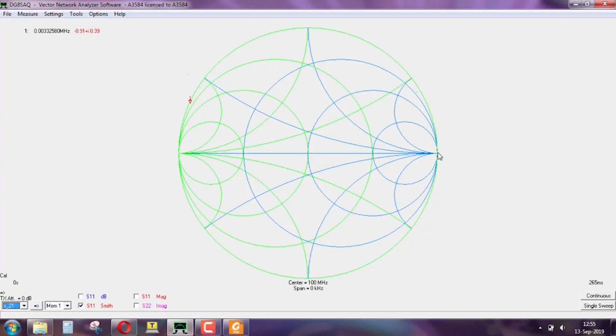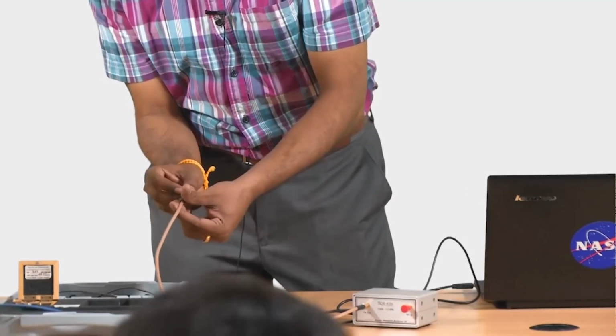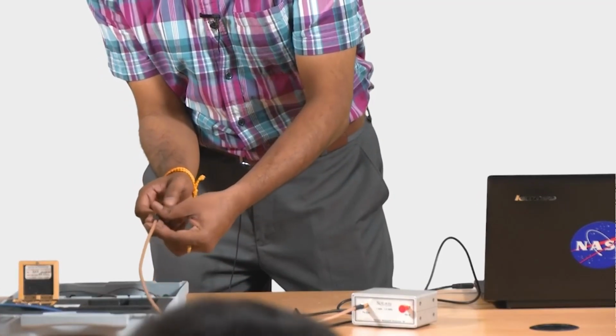because we know that depending on the length of the transmission line, you will traverse around the Smith chart. It will go all the way from a short circuit to open circuit. At lambda over 2 it will keep repeating, we know all that. So now we have a length of a transmission line that is giving you a position in the Smith chart over there. So we can estimate only the electrical length, we cannot estimate the actual length of the transmission line. Now just to make it abundantly clear, what we can do is we can also add another section of the transmission line to this.